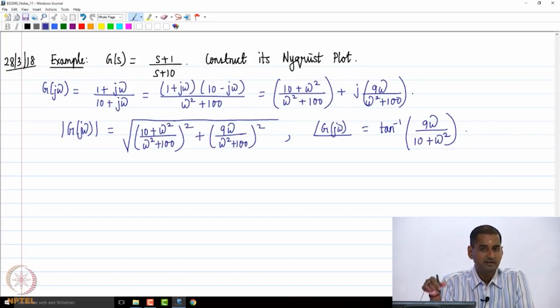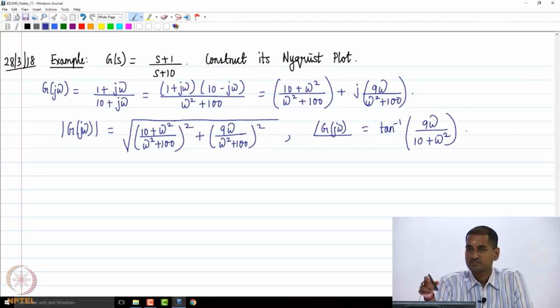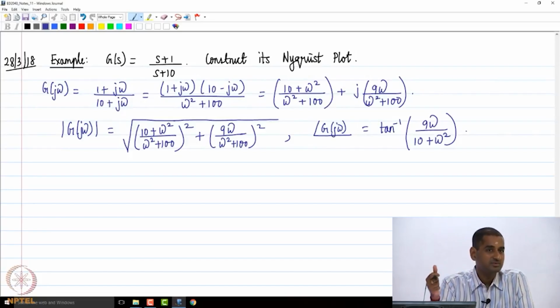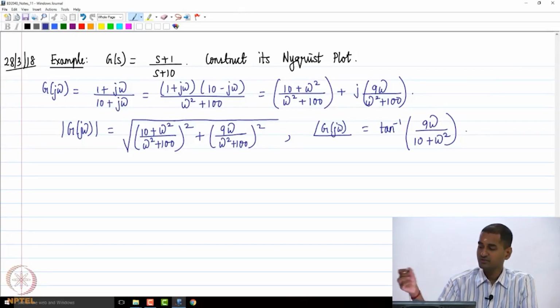So once we process the sinusoidal transfer function, as we are discussing, when you want to plot the Nyquist plot, you also create a table and start substituting different values of omega that you think are critical, and start calculating the real part, imaginary part, and so on, so that you get an idea as to what would happen as these functions tend to those frequencies.